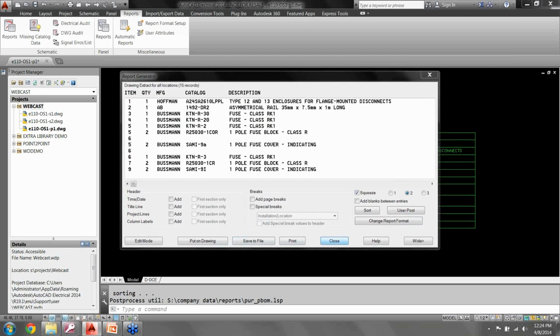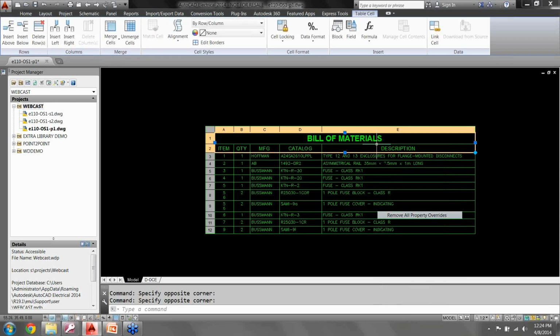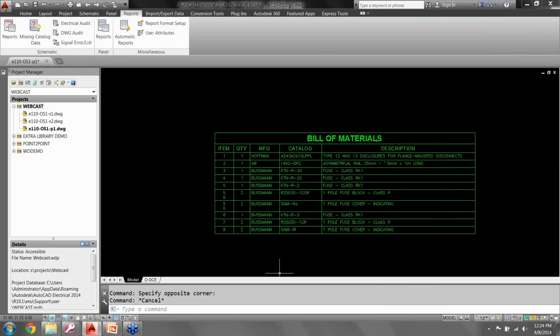My bill of material is really set up to be a single bill of material for per item numbering. But what happens in my per item numbering one, when I get those assembly codes, you can see right here 5 through 6. I got what I want on items 6 and 5 right here. But see here, I've got item 5 and 6, and item 5, 6 again for the holder and for it. So with this, I can see that I've got 2 of these coming and 2 of these coming, but my item numbers are kind of confusing because they use the same item number.